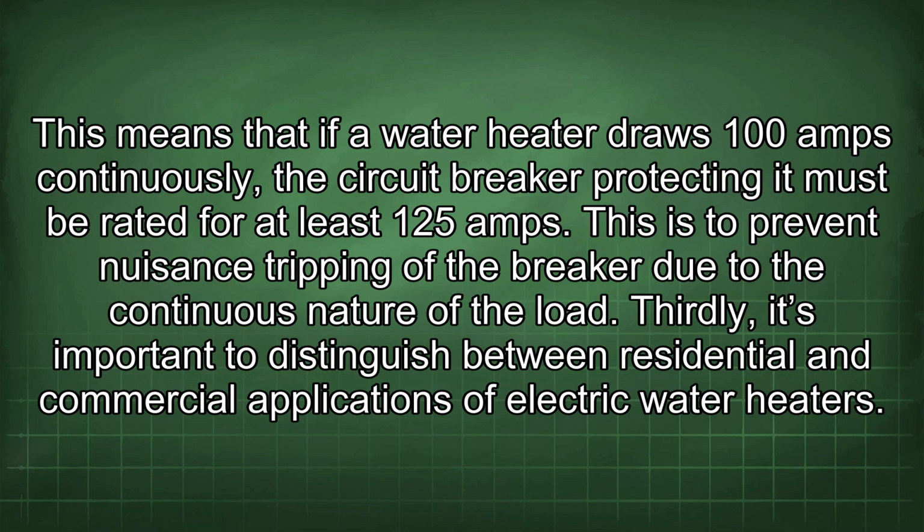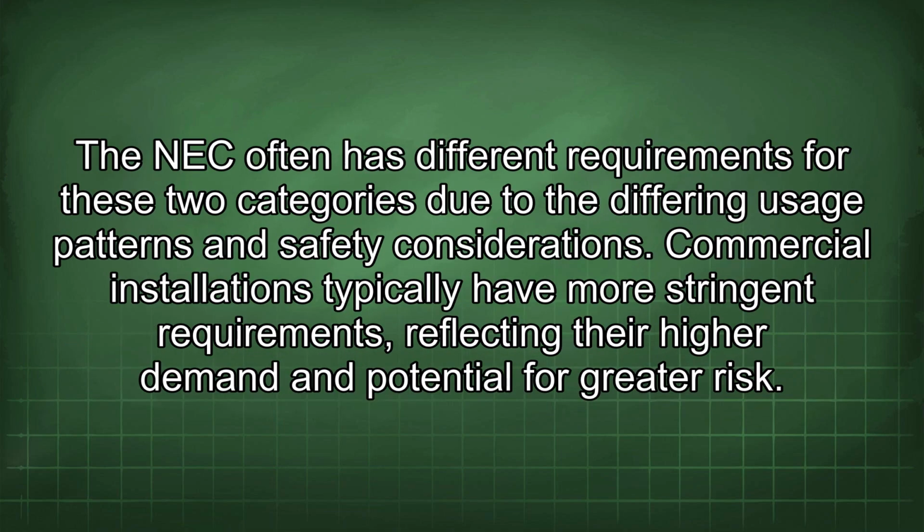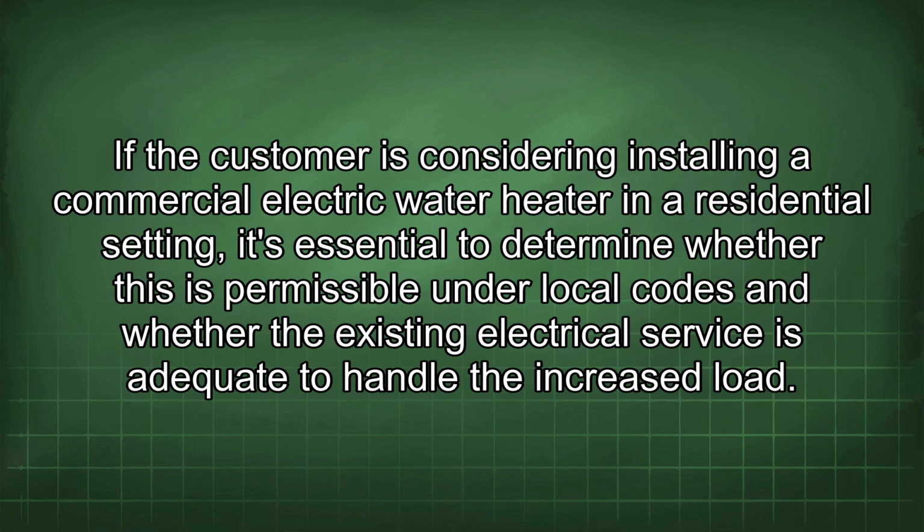Thirdly, it's important to distinguish between residential and commercial applications of electric water heaters. The NEC often has different requirements for these two categories due to the differing usage patterns and safety considerations. Commercial installations typically have more stringent requirements, reflecting their higher demand and potential for greater risk. If the customer is considering installing a commercial electric water heater in a residential setting, it's essential to determine whether this is permissible under local codes and whether the existing electrical service is adequate to handle the increased load.